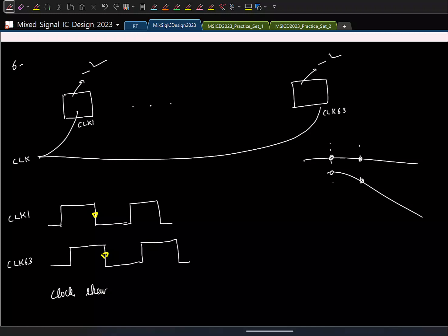And what might happen because of that is, ideally if you take all the 2 power n minus 1, or the 63 output bits, you expect a string of zeros and a string of ones like this, right? But now it can so happen that, let us say for this guy, the input getting sampled for this comparator might be slightly different. So it might make a decision based on a different input. So this by error can become 0. Others could be 1, let us say. Just giving a sample example. Okay. So this is called bubbles or sparkles for obvious reasons.